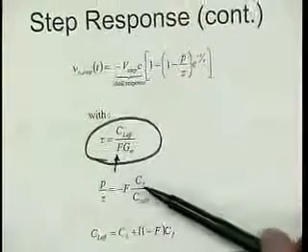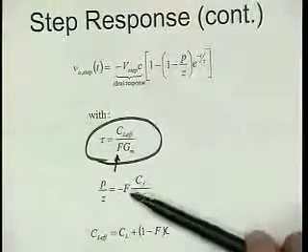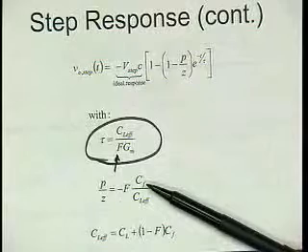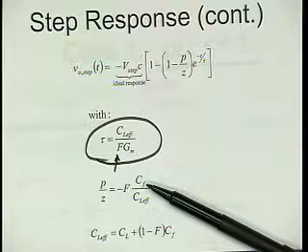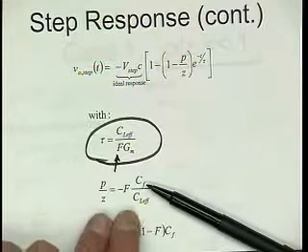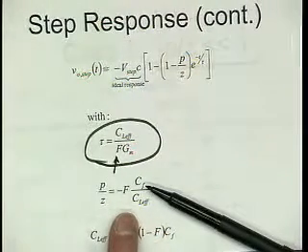So first of all it's the feedback factor F. Well, if we want to realize large gain, right, 1 over F, well, the feedback factor is always smaller than 1 over C, 1 over the closed loop gain. So if we want to have a huge gain, C, then that means that F is going to be very small, even smaller than 1 over C. Right?